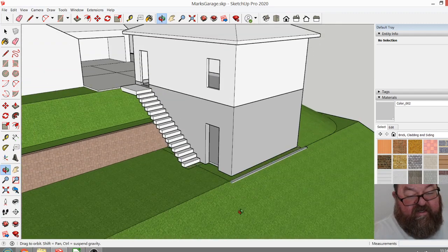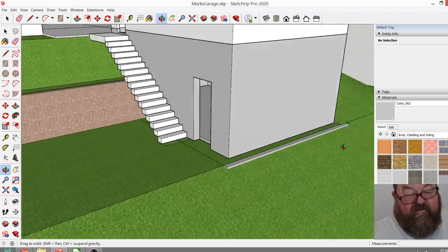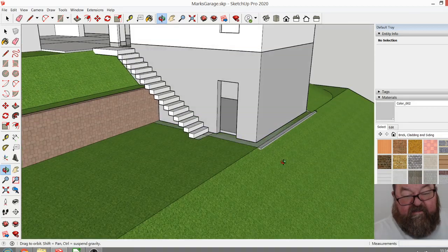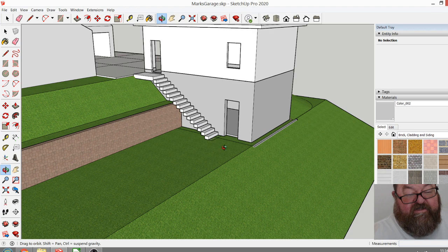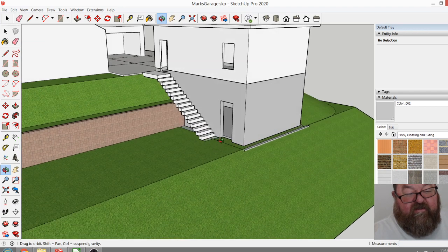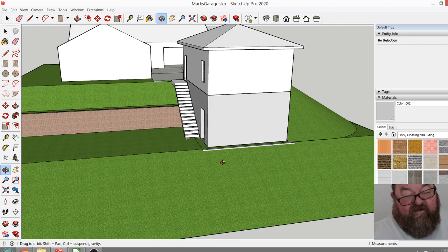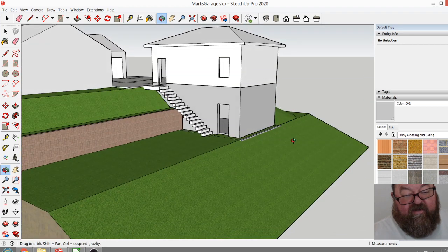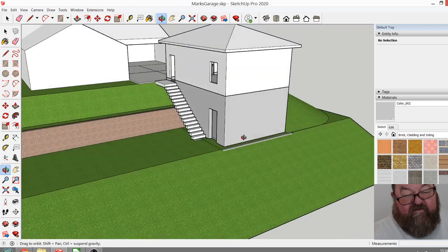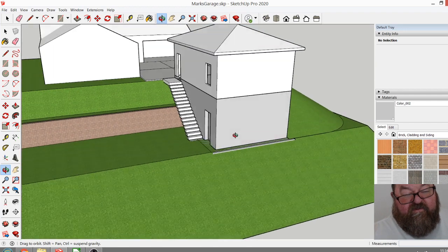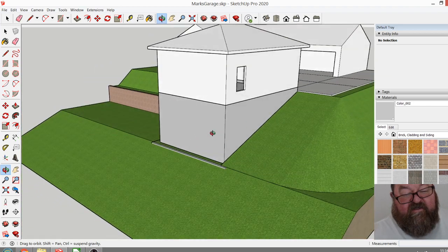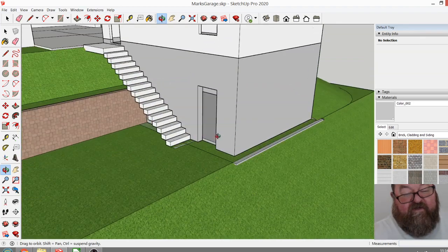The reason I was putting it around here is because you're on a slope, right? And this part of the grade is going to have to be leveled off anyway, or it's going to be cut out anyway. So you could dig yourself out a level spot here just to have a landing coming down, because otherwise if you put doors back here, you're going to have a deck, or you're going to have to grade the ground and it's going to settle. It's going to be problematic having doors back here. You could put windows around, whatever you want to do.